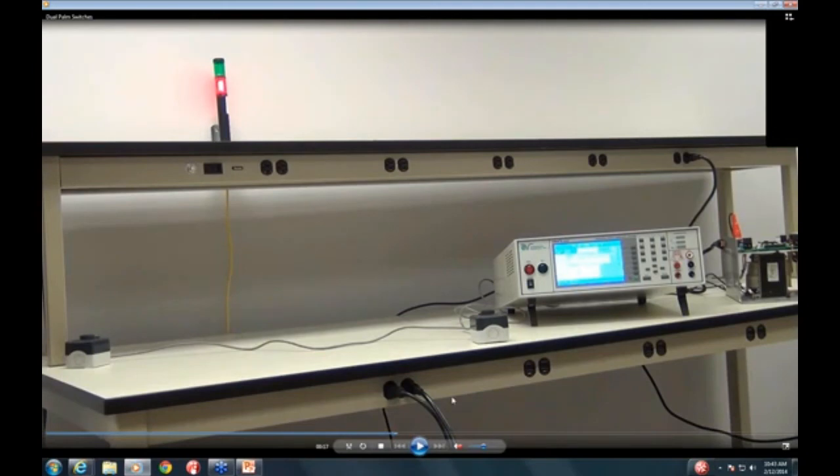I know the screen is a little difficult to see here, but if you look on the HiPot tester, on the bottom right-hand side where there's that white, red, and black lead connections, there's a little HV symbol. When I start the test, you'll see that flash indicating that high voltage is outputting. So basically what I tried to do is cheat and push the test button, but I have my PLC remote activated, so it's not going to let me do that. I have to use those switches.